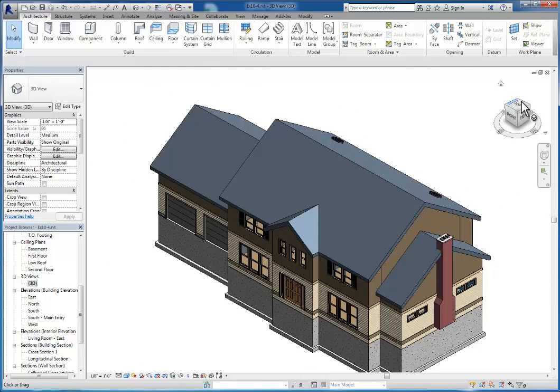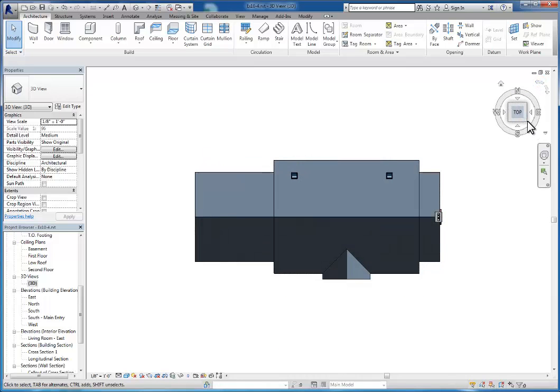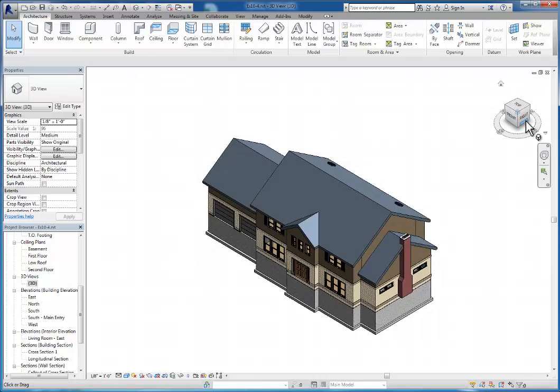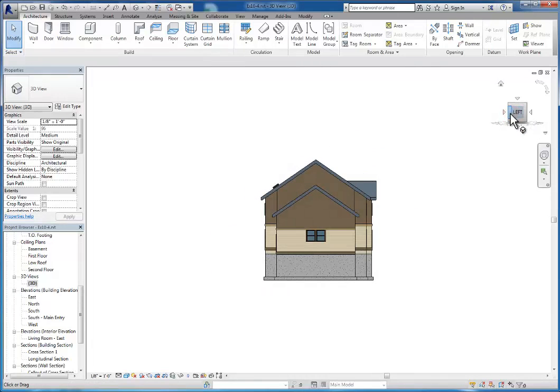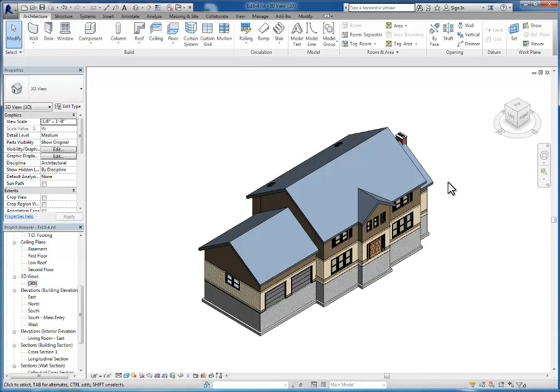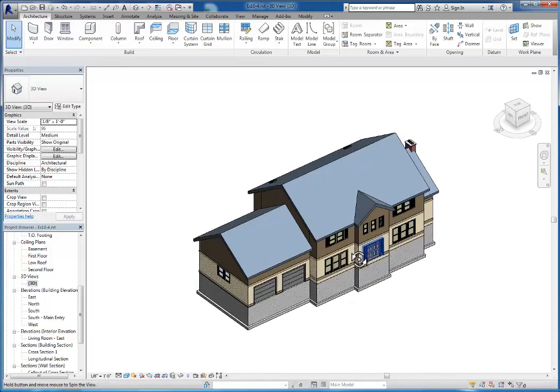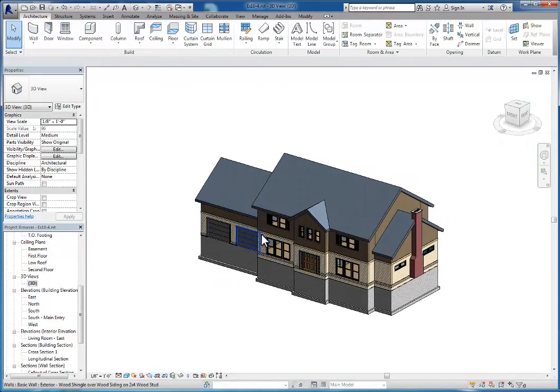The big advantage with the view cube is I can click on certain views. If I want to view it from the top, maybe rotate it around, maybe do a southeast isometric view, I can click on the specific edges or corners or faces to look at particular views in 3D. So that's the big advantage to the view cube. But again, if you're orbiting, I would just recommend holding the Shift key and pressing the mouse wheel down and moving your mouse. I think that's the fastest way.